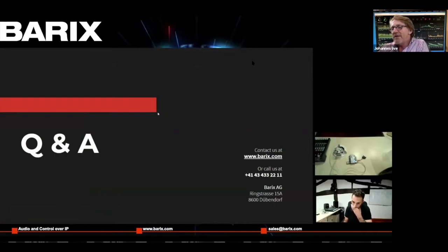And in the general market, one of the big sensor interfaces, of course, is contact closure. One of the biggest sensor interfaces is 4 to 20 milliamps. And if you look at the spec sheet of the Barionet, it doesn't talk about 4 to 20 milliamps. It just talks about 0 to 10 volts. So one of the things I would like to give you on the way here is if you have 4 to 20 milliampere sensors, they work on the Barionet very, very easily.